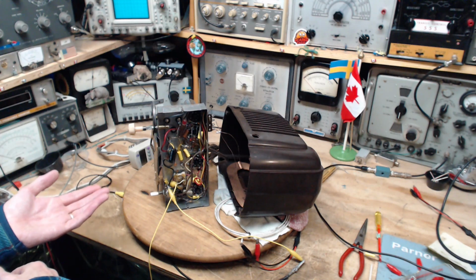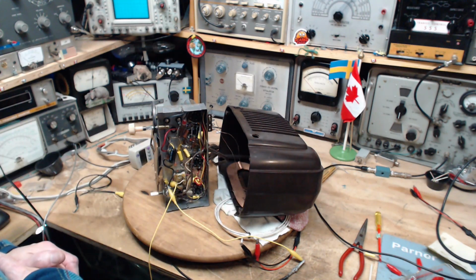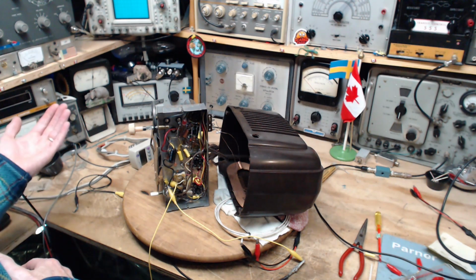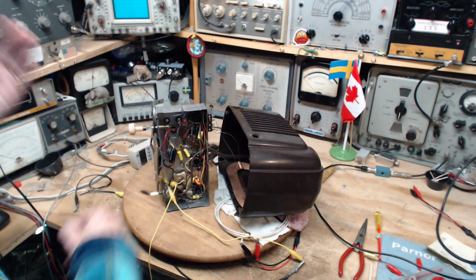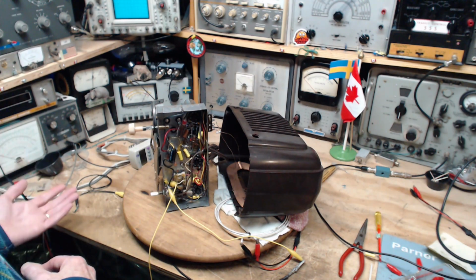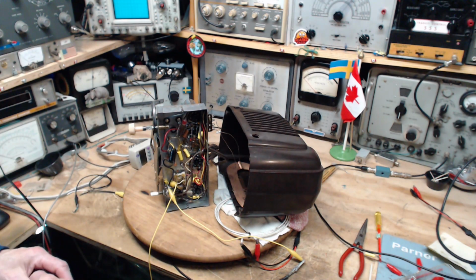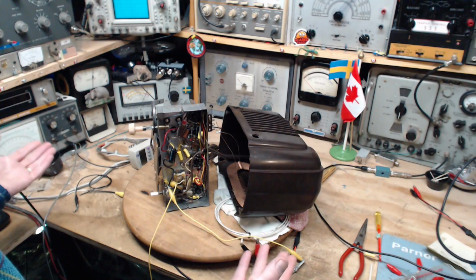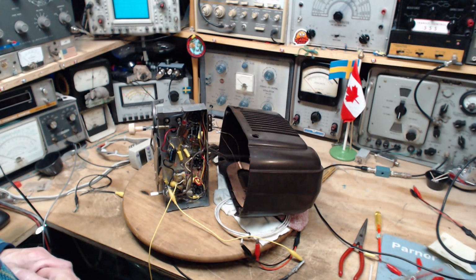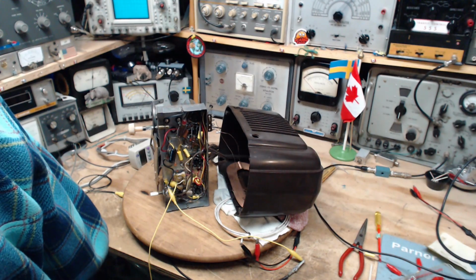When I started on the radio, the IF was tuned way off. Maybe there's a reason for that. As for knowing that it's gone, the SDR may show something, and then I fiddle and something's no longer there. Knowing that it's gone would be picking up a station, tuning it in, and not hearing the heterodyne. I think that's proof positive too. So that's the approach I want to take. SDR. Let's get the SDR. Okay, I'm going to stop the video. I'll get everything set up, and we'll do this.